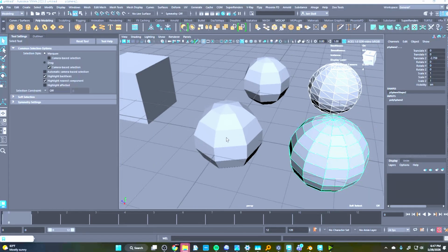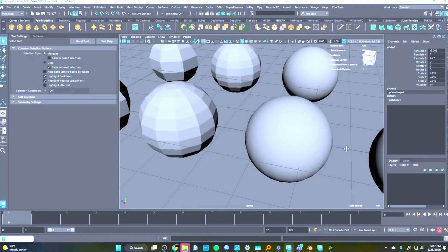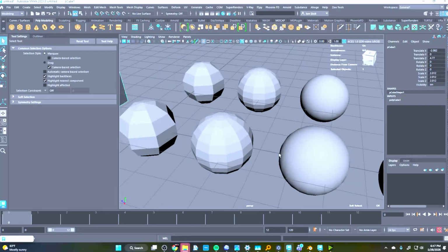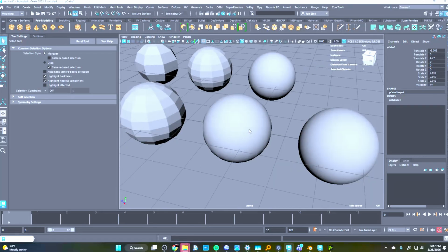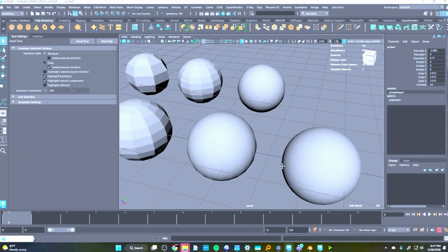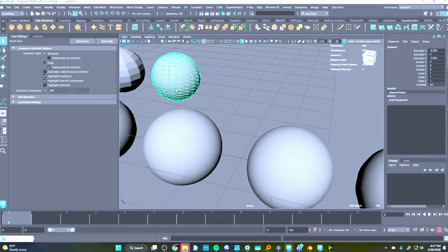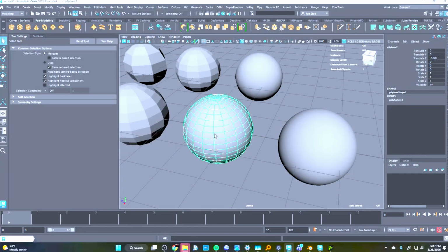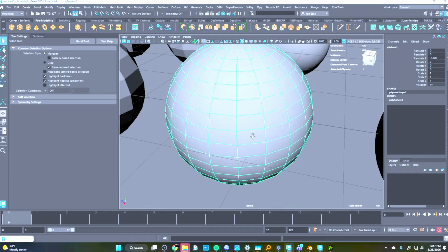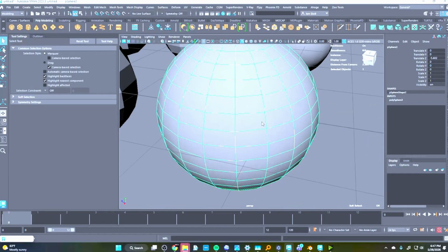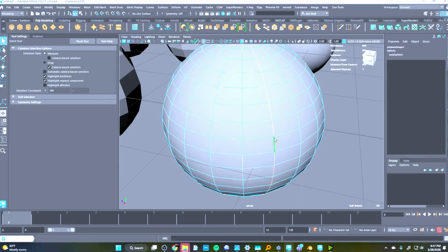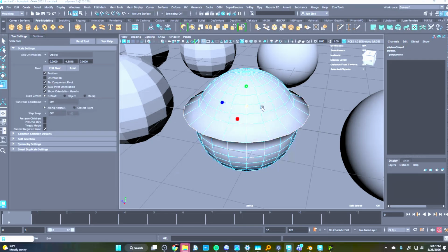Polygons are made up of four-sided and three-sided faces, and you can even do five-sided, but it's not suggested. You can do a lot of sides, but they run into issues later. So if you're a really good modeler these days, you want to make everything with polygons. Part of the reason is that when I'm selecting and working in this application, I can select this edge loop, this whole string of edges, and modify it and do stuff with it.